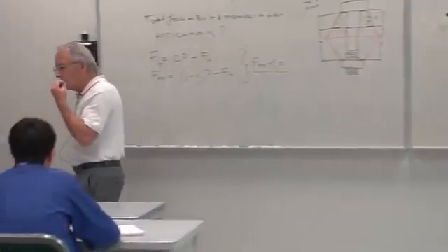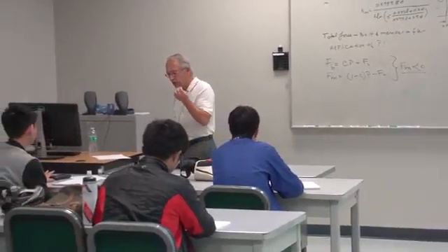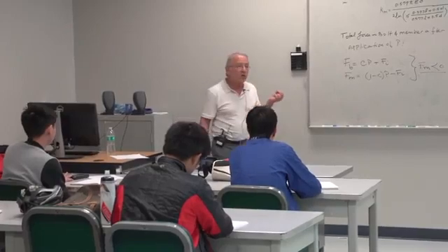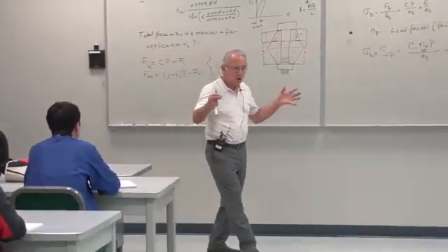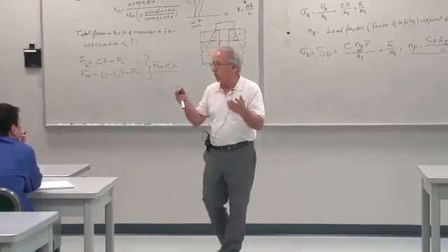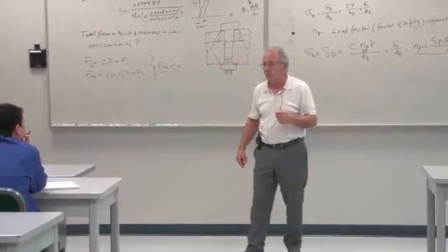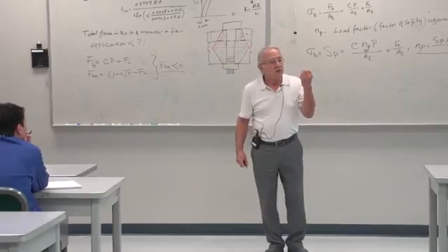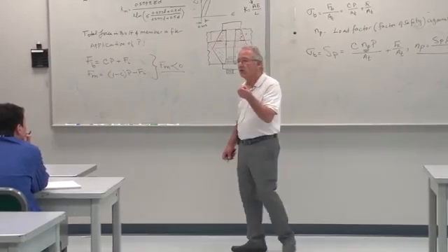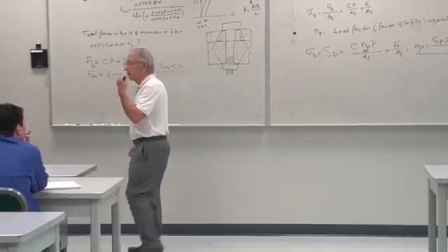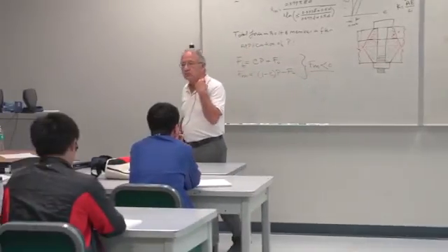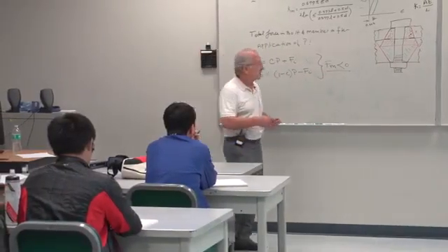A good measure is for reusable connections, like pressure vessel heads, that you put on, take off, change gaskets, what have you. Use 75% of the proof strength as your preload, or preload stress.